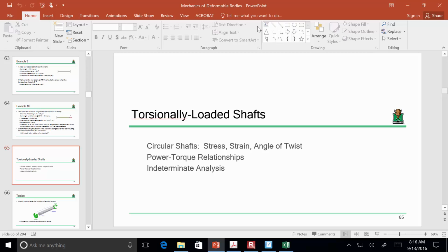Okay, so let's say it displaces 2 inches. I'm then going to say, okay, given this series of pipes, how much do I have to yank up on it to pull it up 2 inches? And then whatever that value is, that's going to be the reaction at A. Then I can use equilibrium to get the reaction at B.